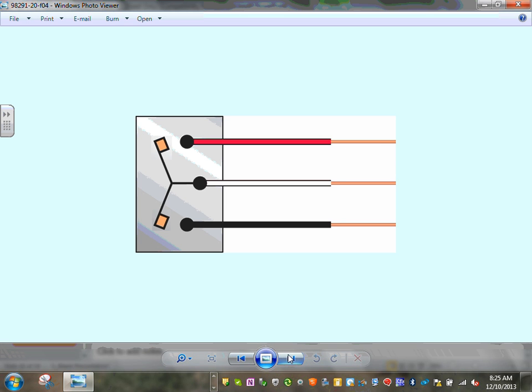Here's the low voltage switch, Adam, how it works. Every low voltage switch needs 3 wires. Unlike the regular switches, how many wires do you need in a regular switch? 2 wires, right? One to energize the switch, the other one to go to the light. This needs a common. Can you guys see that? Red is off, black is on, and that white color here, typically blue, would be the common. They call it the common.